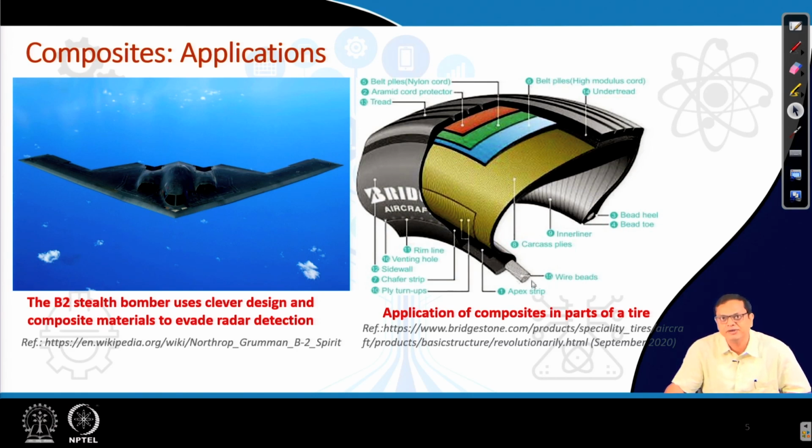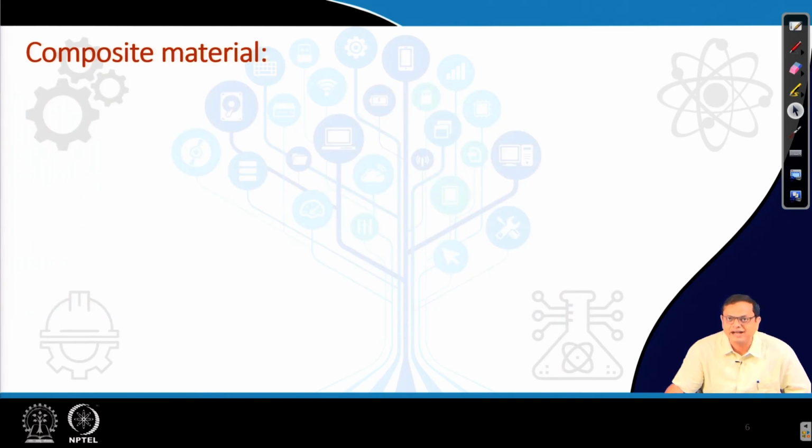Similarly, you can see here around the periphery of tires these bead wires, which are made of steel and coated with tin or copper-tin alloys, in some cases copper-tin-zinc alloys. These steel wires, called bead wires, are also used to reinforce the radial tires.